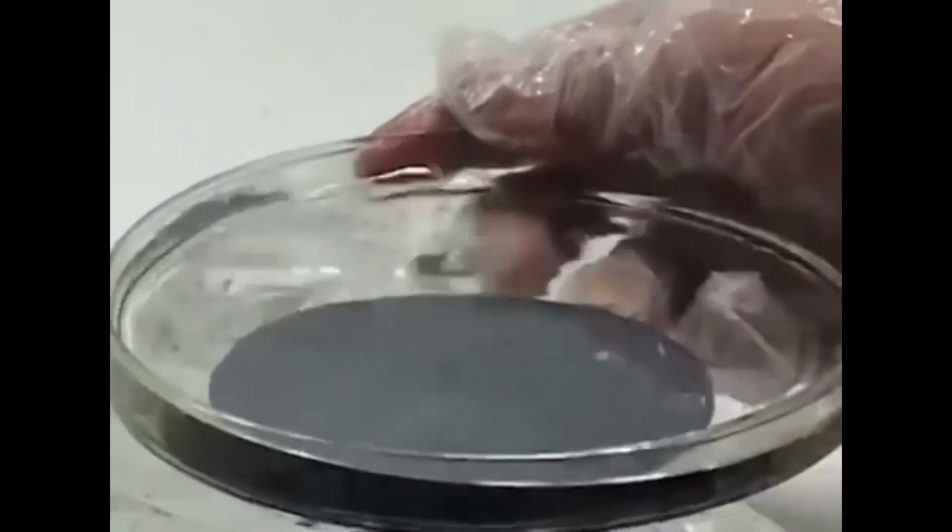We need to do a proper microscopic analysis later on, but this really is the success of the process. It means that whatever you have exposed is staying there, the resist is all cross-linked, and the remaining portion has been removed. Again you have to keep circulating this and spraying isopropanol from time to time to see whether everything is remaining on the surface.